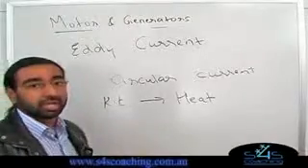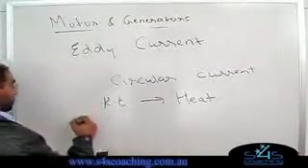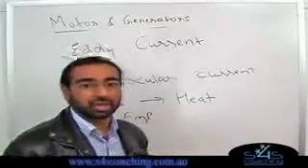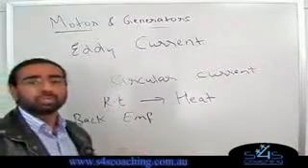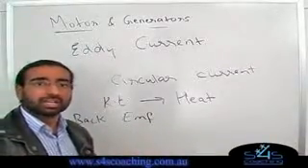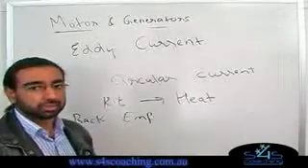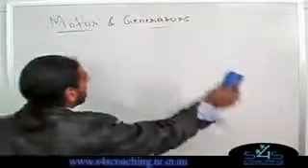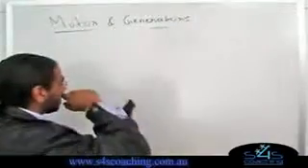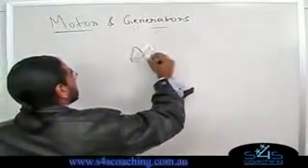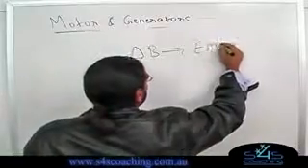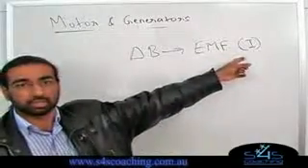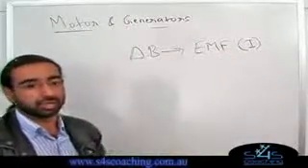The last thing we're going to have a look at today is back EMF. Now, let's have a look at the example again. Back EMF is the voltage that is produced in a conductor that tends to neutralize the present voltage. What does that mean? Think of it like this. We just learned Faraday's law of electromagnetic induction. What that states is that if I have a changing B, then I will induce an EMF/current. So a changing B will produce a current. As long as there's a changing B, I'm going to get a current.